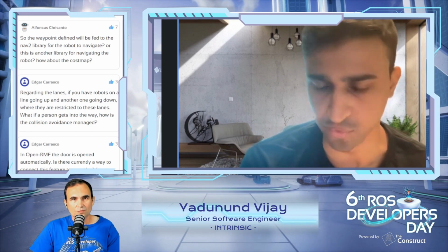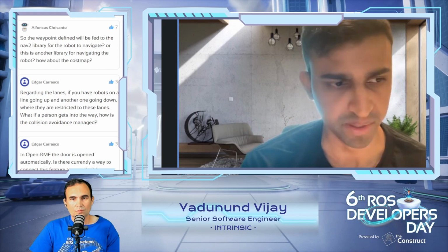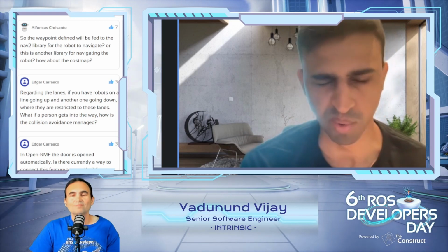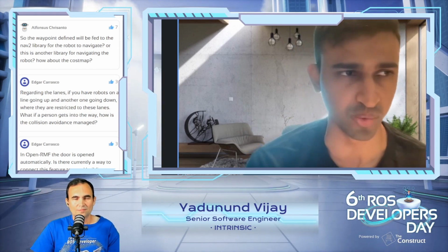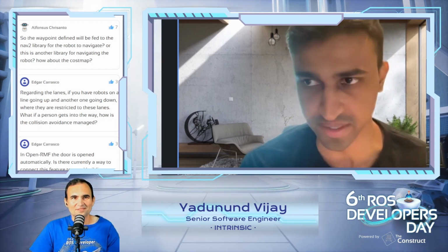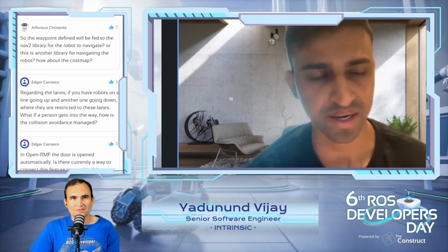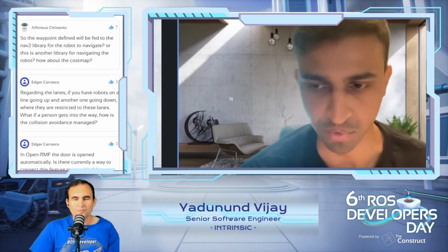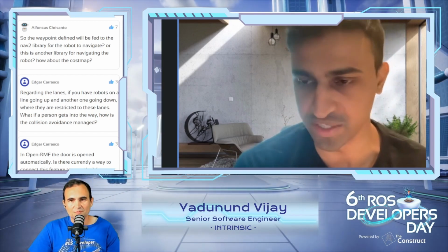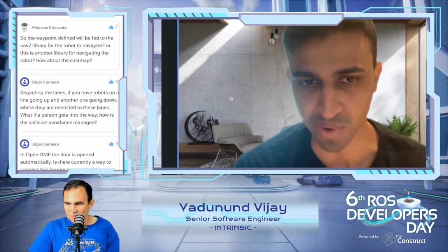But I want to emphasize that this is purely for the simulation we are running now. If you want to run a simulation with a full navigation stack, that is totally possible. We do it this way because we want to save compute resources. When we run RMF, we typically have 10, 20, many robots running, and it's hard to have the compute resources to simulate all of the robots if each of them has a navigation stack. Since we're more focused on coordination and orchestration between robots, we assume that whatever navigation stack the real robot has will be in charge of moving the robot from one waypoint to another.